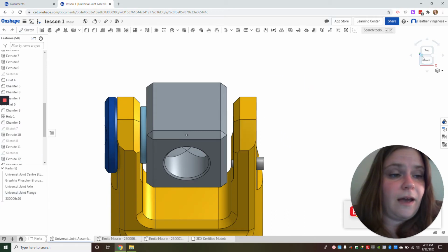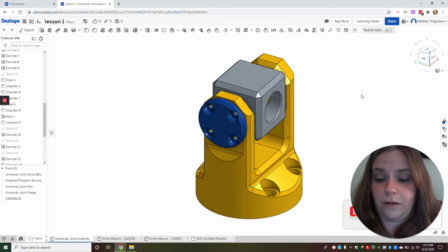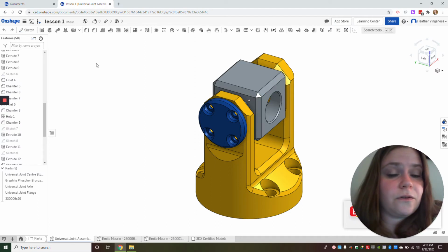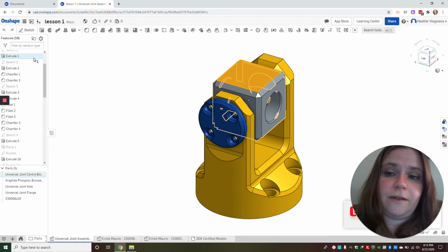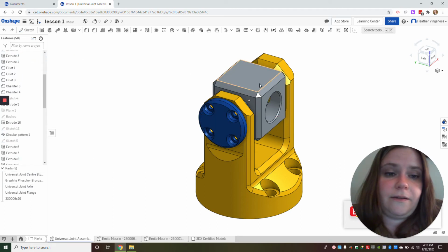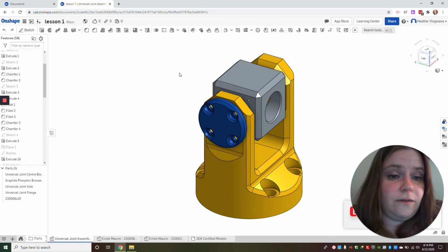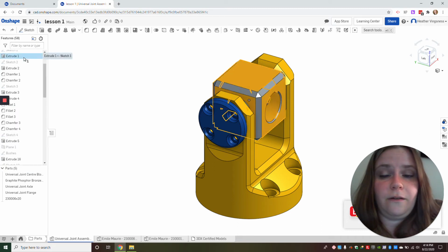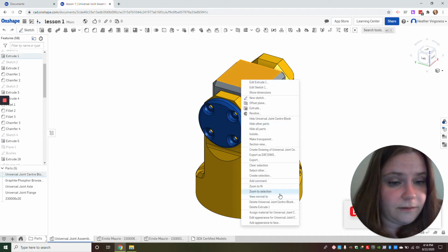I'm going to click this top corner so I can go back to what I expect to be my normal view here. If I want to select things, there are two ways to select things. I can either draw a box or I can click on them individually. By clicking on parts individually, you'll see that it highlights over here which part you have clicked. So this is part 8, this is part 1, for example. If you click on it again, you can deselect it. You can do the same over here, select and deselect. Another way of deselecting is to click and clear your selection, like this.